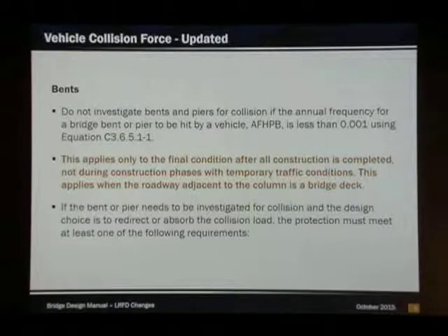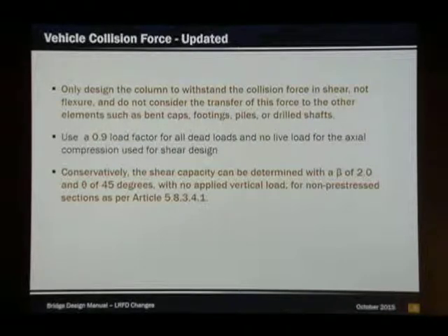If the bent or pier needs to be investigated for collision and the design choice is to redirect or absorb the collision load, the protection must meet at least one of the following requirements. Only design the column to withstand the collision force and shear, not flexure, and do not consider the transfer of this force to other elements such as bent caps, footings, piles, or drill shafts. Use a 0.9 load factor for all dead loads and no live load for the axial compression used in shear design.